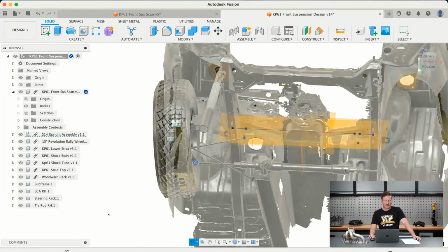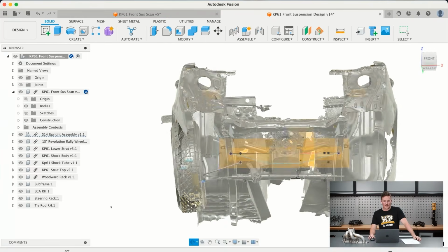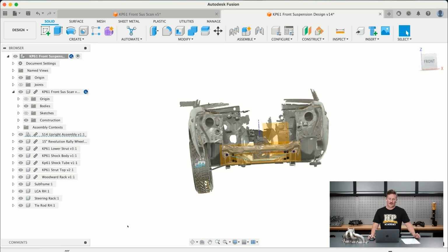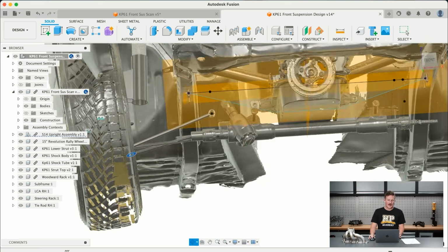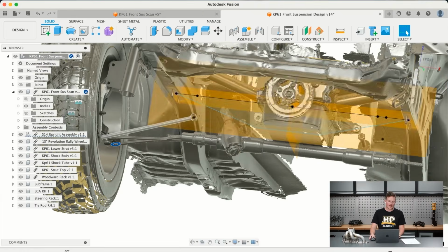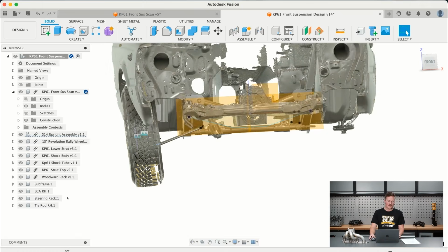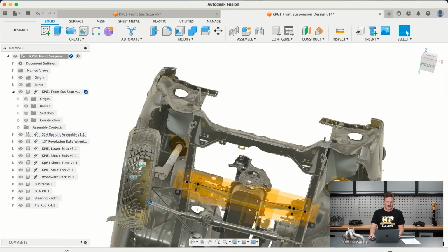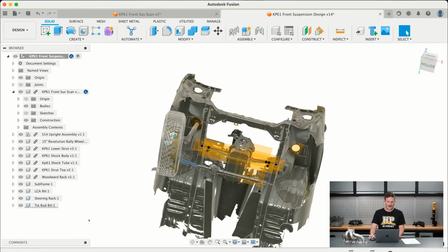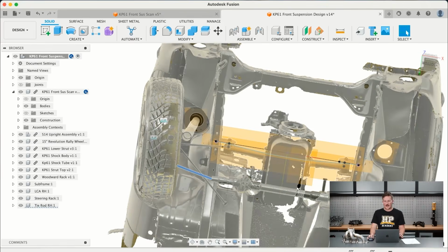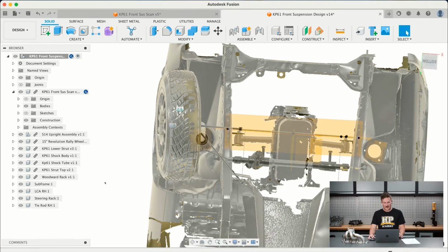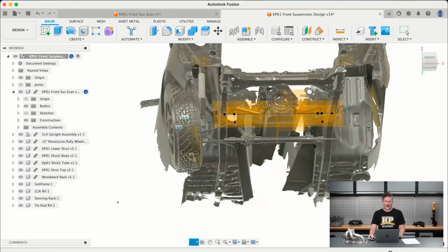We can just start planning out some points in space. And then once I get this a little bit more suitable, where this lower control arm is nice and flat and we don't have positive camber on this arm, I can adjust the length of this tie rod end here to get the toe closer to zero, because it looks like it's massively toed out at the moment.